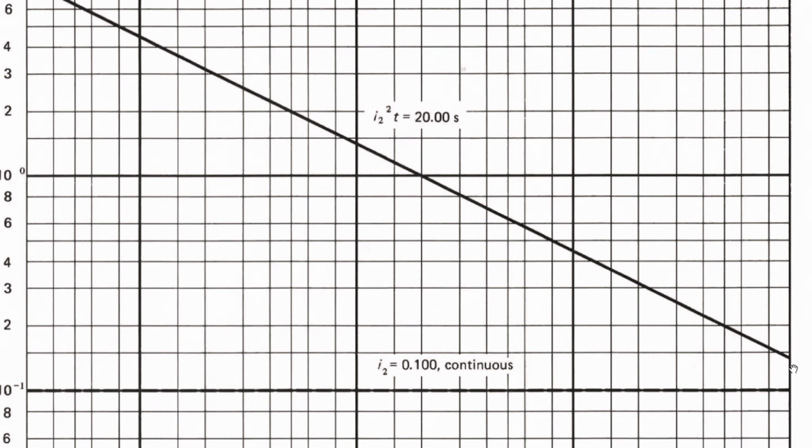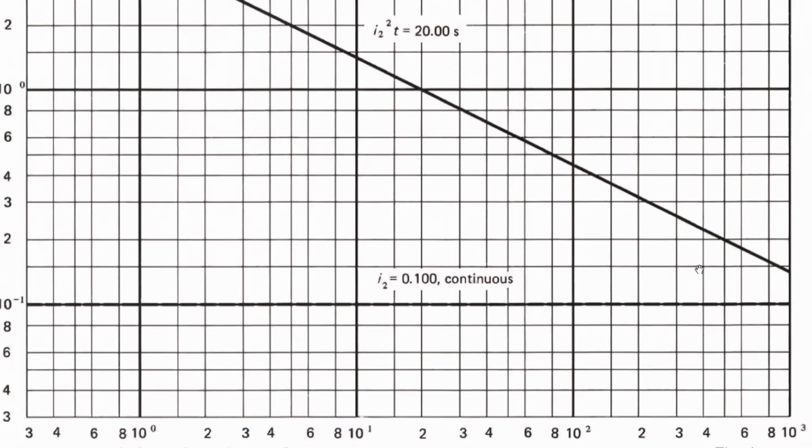When the current is less, we give more time to operate the generator with this fault, so that maybe during that time the unbalancing resets automatically and we don't need to open the breaker. But if the negative sequence component magnitude is very, very high, the breaker will open immediately, within a few seconds or milliseconds.